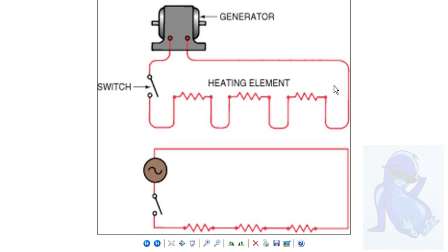This is called a series circuit because everything is strung together in series, just like Christmas lights. So if you break this line right here or anywhere, if a bulb burns out, they all stop. L1 to switch, switch to load, load back to L2. Series circuit. This same circuit can be drawn much more simply as a rectangle.